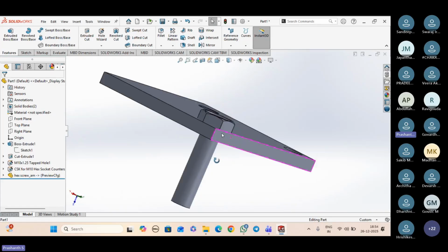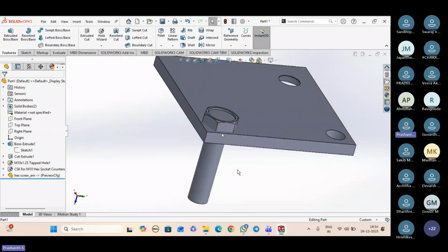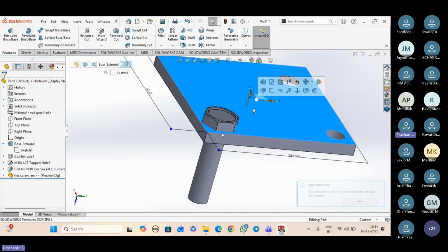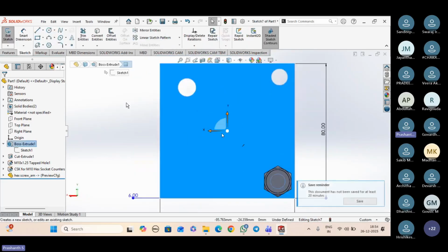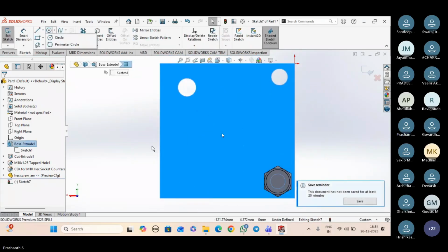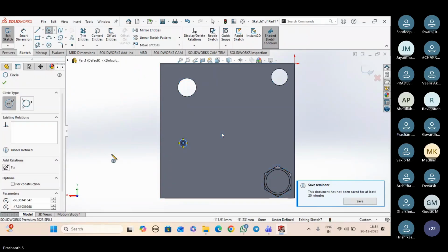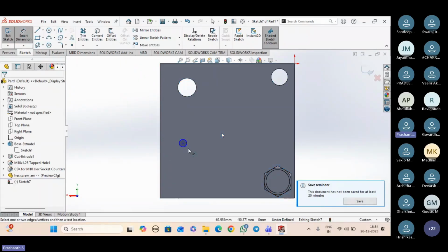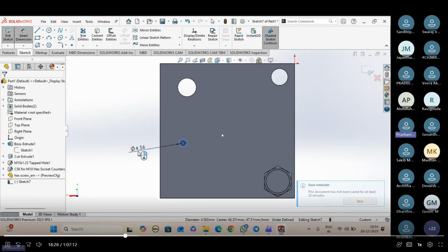So like this, how is this diameter fixed? See, that is picked based on the hole size that we are referring to. If this hole is, let's say, some smaller one, let us make a smaller hole here. Say M4, 4 mm.